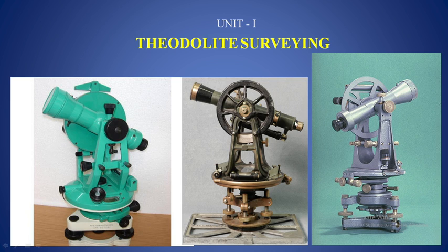the telescope truly horizontal. Here it means keeping the telescope truly horizontal means keeping the vertical circle to 0 degrees. So by keeping the vertical circle to 0 degrees, you can take the staff readings and you can determine reduced levels of the ground, just as the dumpy level.